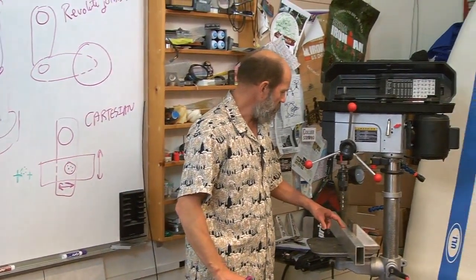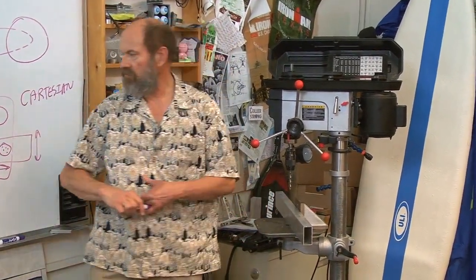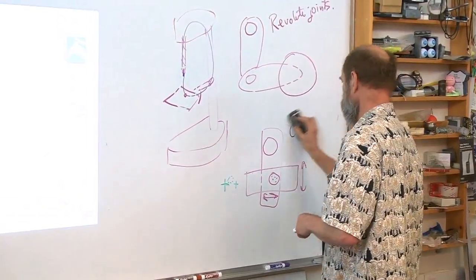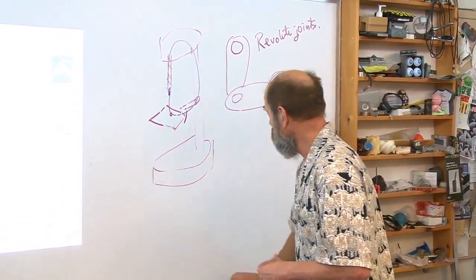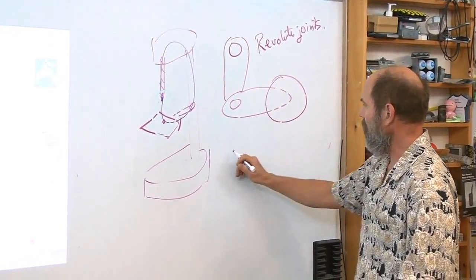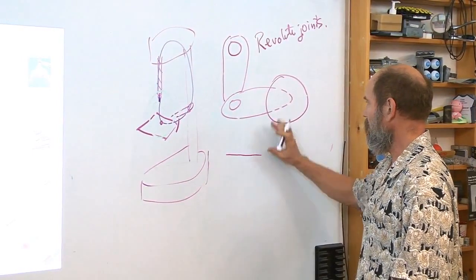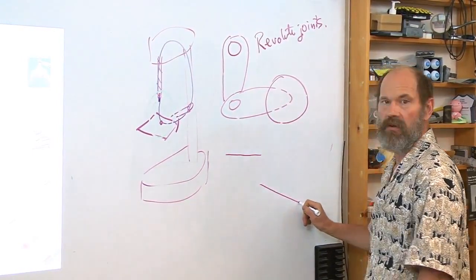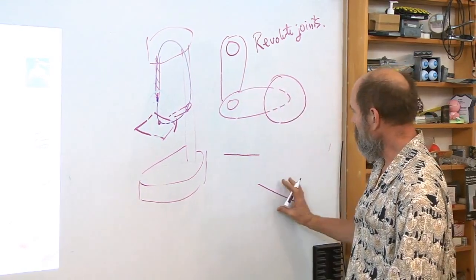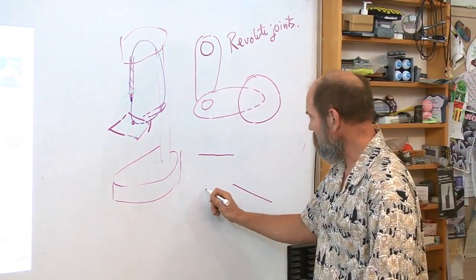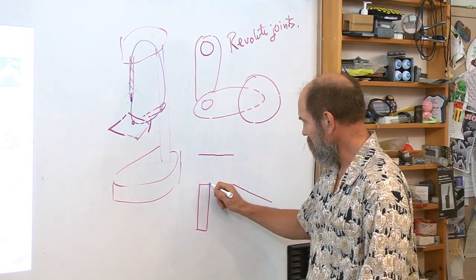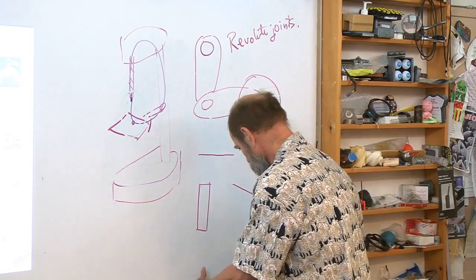When I drill a hole, most holes are to be positioned, and we're going to pick this guy, the revolute joint design. When I position this, if the table in this position is horizontal, and as I move it, the table is then at an angle, because of the slop in the joints. Why might it do that? Well, let's look a little bit more carefully at a joint. A revolute joint will have an axle or a pivot,